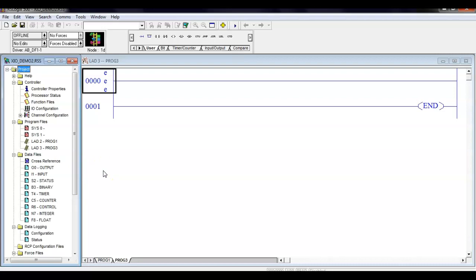So these other files, anything above data file 1, we can make multiple of these. Anytime we use these, in an instruction we're going to have to specify the number. Now this is the biggest difference with newer PLCs. With RSLogix 500, the application controls the memory of the PLC.